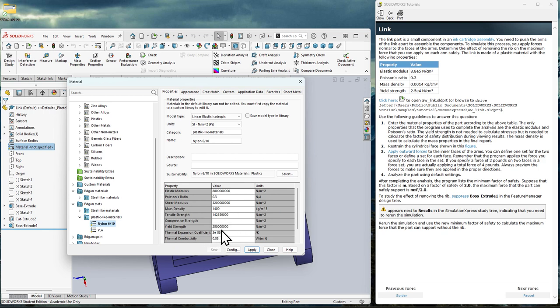And the yield strength. So yay, that made it easy. But ultimately, just make sure you use Google and convert these to the appropriate units, because this is a Newton per meter squared. These are Newton per centimeter squared. They just want to make sure that you're paying attention, I think. So these were the correct values here on my screen.